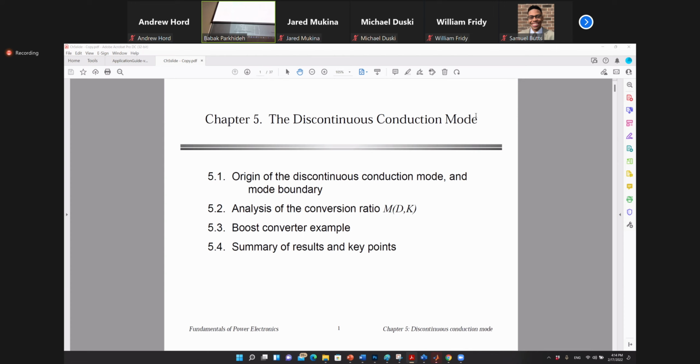If you look at that slide, that diode is only engaged if there is no gate. Because once you create the channel, you actually have a MOSFET, a majority carrier device. In other words, it doesn't matter if the current is positive or negative, it's not bipolar. So it doesn't matter left drive or right drive. If you operate this converter synchronously, then you don't engage this diode, and now your circuit is different.